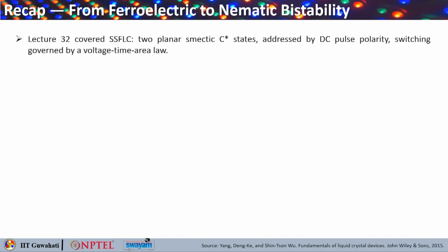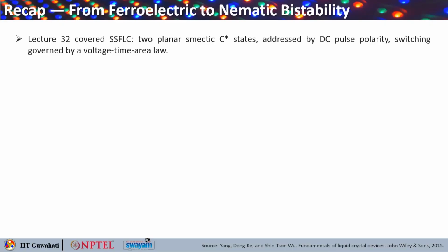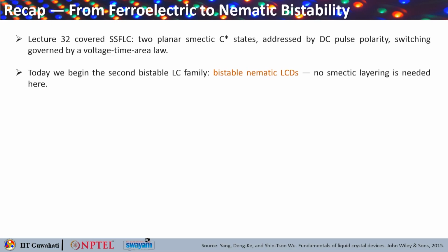So here is a brief recap from the previous lecture where we covered SSFLC, that was basically having 2 planar smectic C states addressed by DC pulse polarity. Switching was governed by a voltage time area law. So today we begin the second bistable liquid crystal family. We'll talk about the bistable nematic liquid crystal displays.